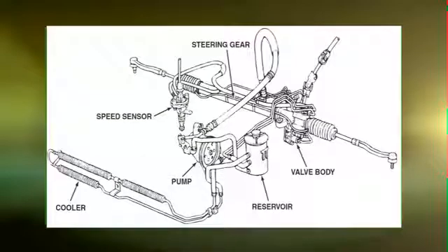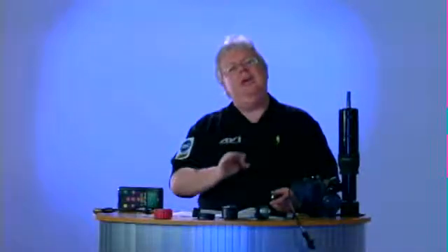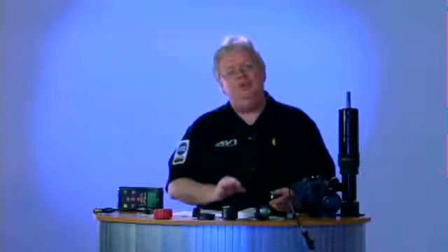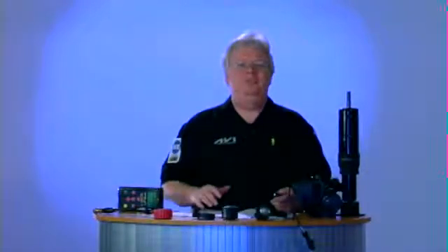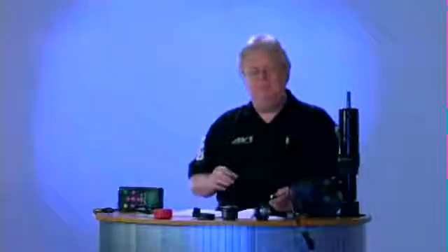Now, because we're going to be pumping high pressure hydraulic fluid, we have a pressure line as well as a return line back into the system. It's important you can establish which is which, because you're going to be putting on a power steering pressure gauge when you diagnose the system. We're going to talk about that because there are test questions coming up regarding power steering pressure and testing.